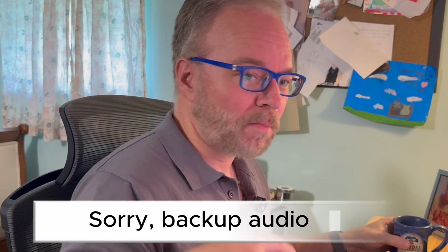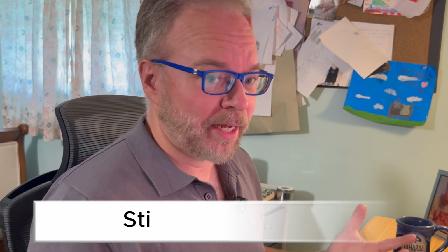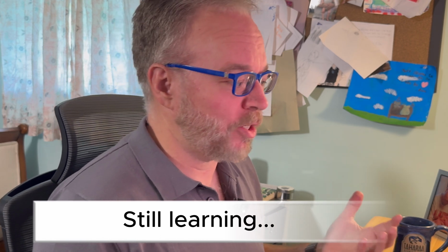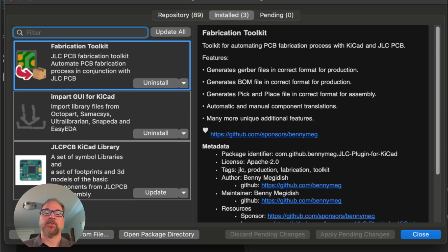This video will walk you through the individual plugins that you need and then the process that you need to follow as you develop your schematic and your PCB layout, to make sure that everything's going to flow smoothly when you finally go to submit it to JLCPCB. So we're going to start out in KiCad and walk through some of the plugins that you need to install to be able to take your project fully from schematic all the way to production. Here's the list of plugins that I installed to support taking your project to production with JLCPCB.